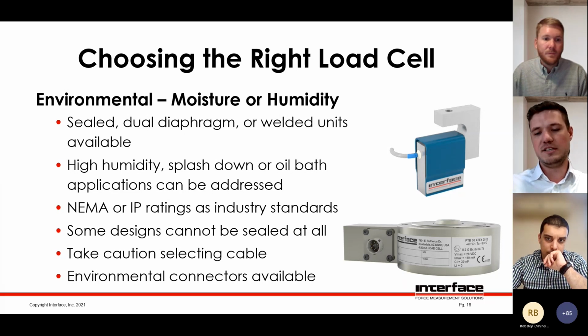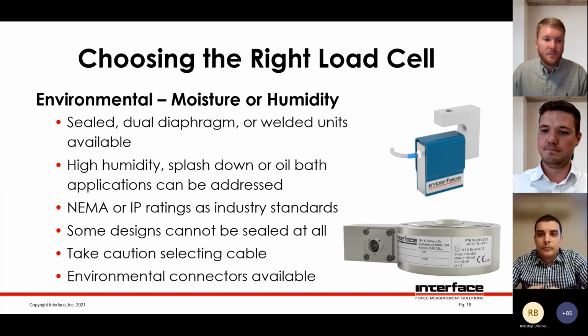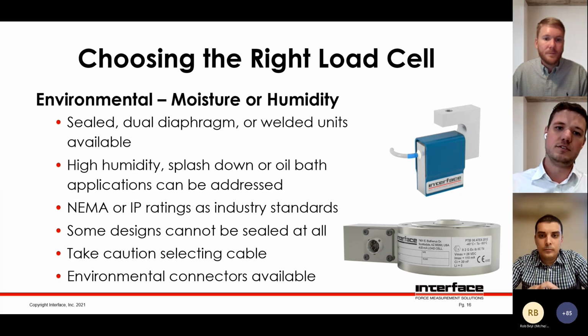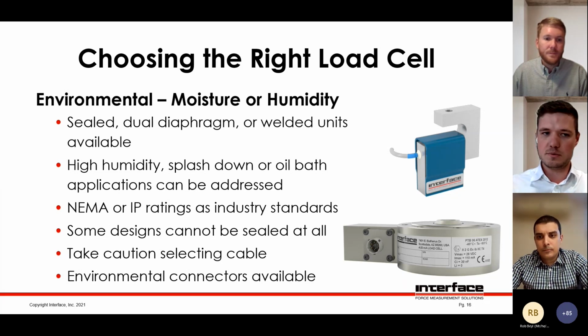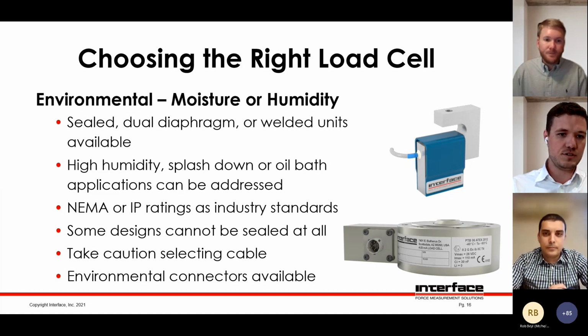Obviously, if it's going to be a noisy and humid or a hot environment, or there's going to be corrosive materials or something like that, we would need to seal the load cell. And that's where you can see the bottom one. That's a fully hermetically welded stainless steel load cell. So it's IP68 sealed. It's also ATEX, I believe. We use IP ratings to verify how well sealed the load cells are. That's kind of industry standard.